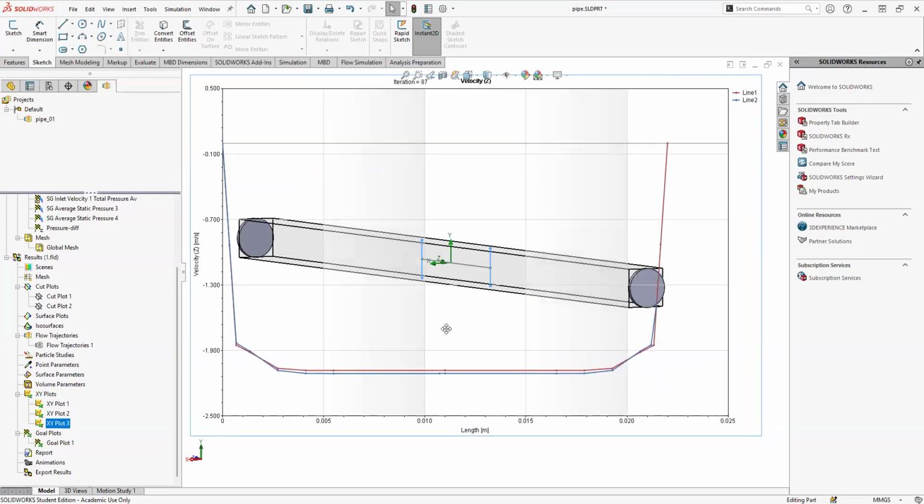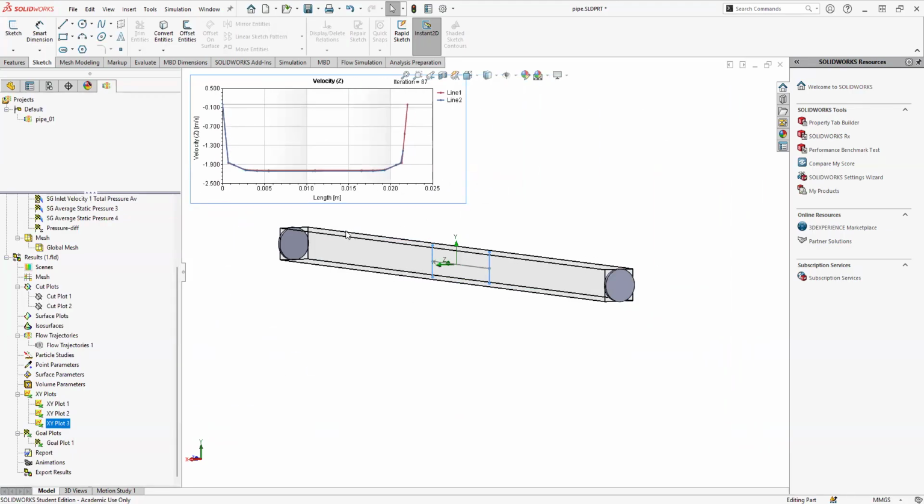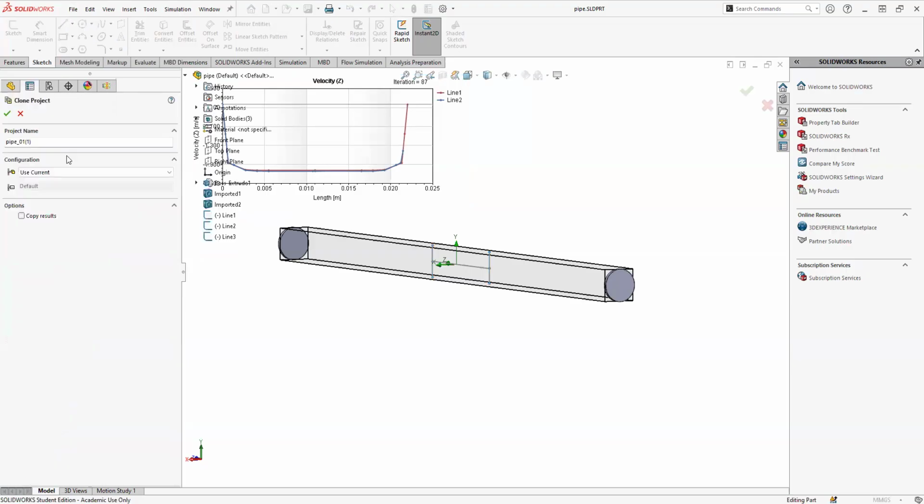Now, let's reduce the velocity and investigate laminar flow, because this is a turbulent flow. You can check that with the properties of the fluid at room temperature, and as well with the internal diameter. So if I want to do this simulation, first save. Secondly, right click on pipe, clone. Clone means it will repeat everything, but you could call that one O2, second simulation.